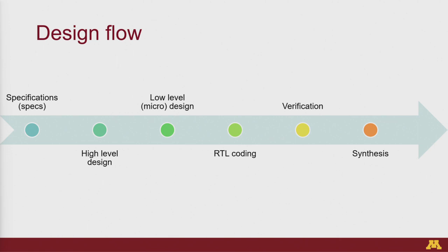And finally, you have synthesis. Synthesis essentially takes whatever you have designed in Verilog and converts that to real life hardware, right? So if you have written the code for an adder, it will actually instantiate an adder with all of its gates and connections within your hardware block.